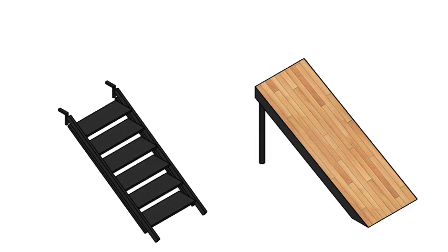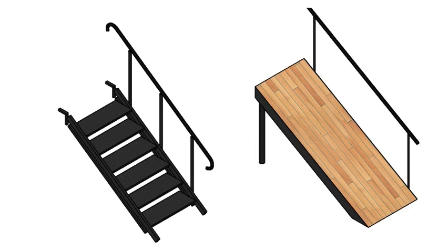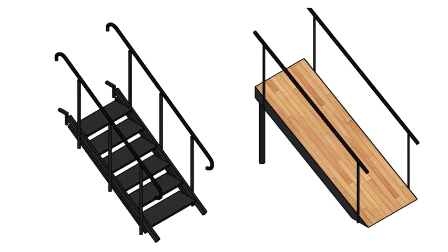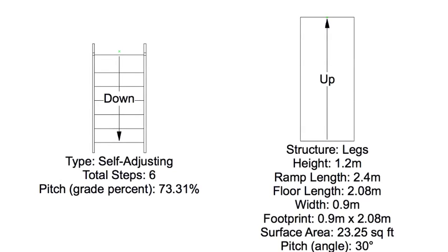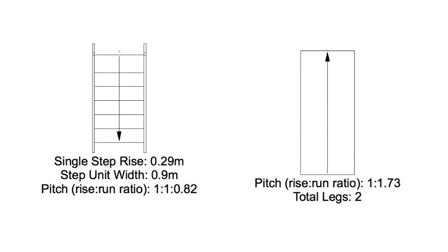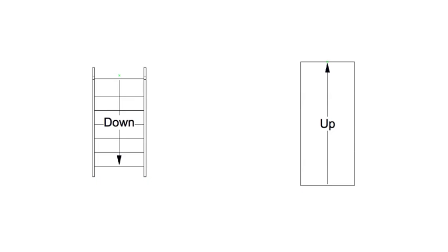For both ramps and steps, you can configure the leg geometry with the same choices available in stage decks and plugs. As with the rails, letting you set either left, right, or both, as well as the individual configurations for each. Each of these last two objects also come with their own set of text options, allowing you to present any needed information directly in plan view, again, automatically calculated based on any changes you've made in the Object Info palette.